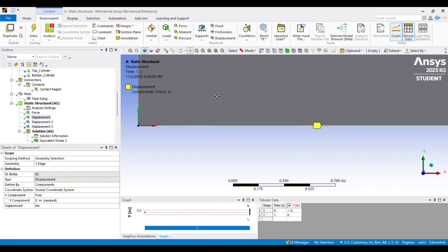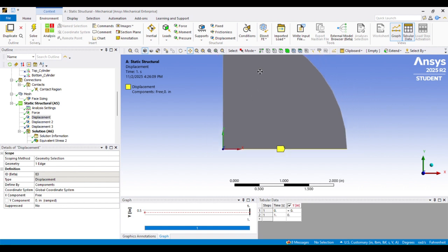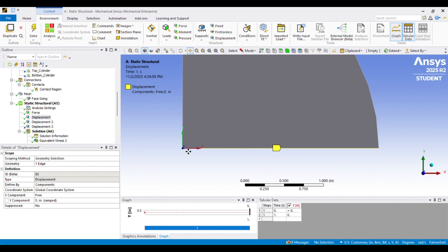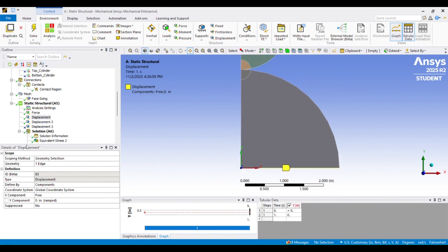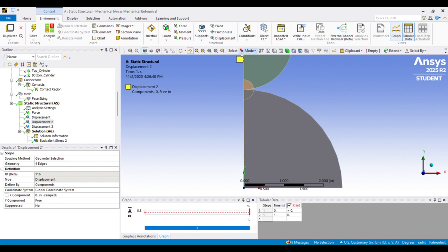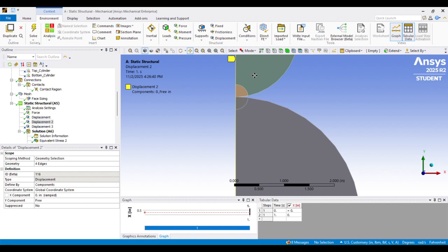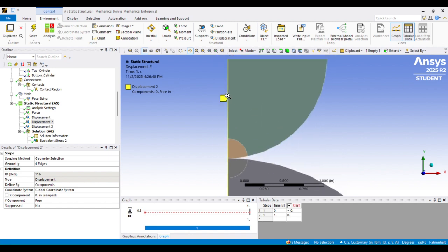And so in ANSYS, if you're in a 2D analysis, there's a few ways that you can run symmetry. You can actually set the displacement by hand, the normal displacement on the edge to 0, and I've done that here. And then I've also set these faces, or these edges rather. Again, our normal vector here, represented by the plane of symmetry, is in the x direction. And I've set the x displacement to 0.